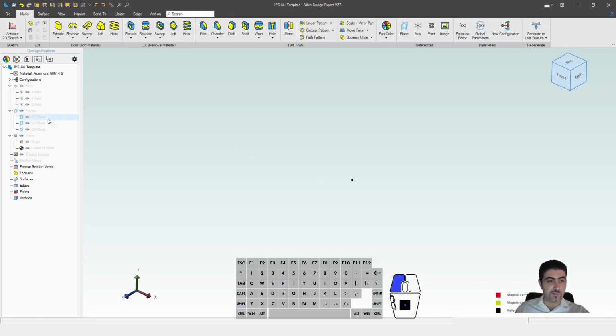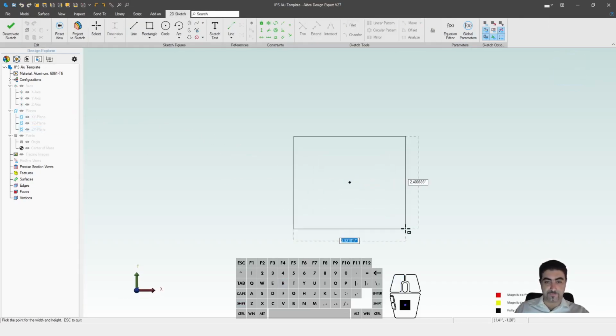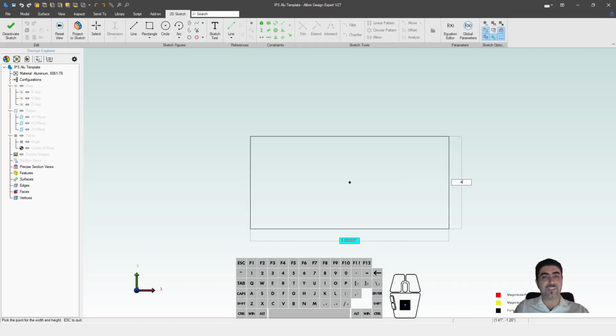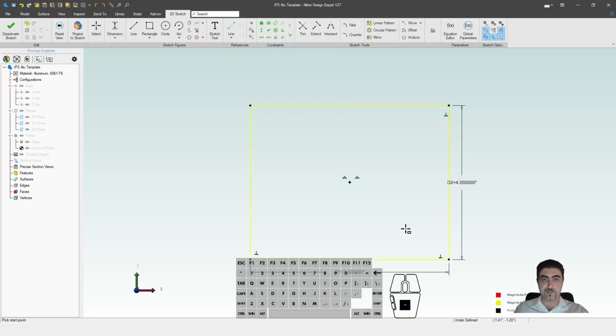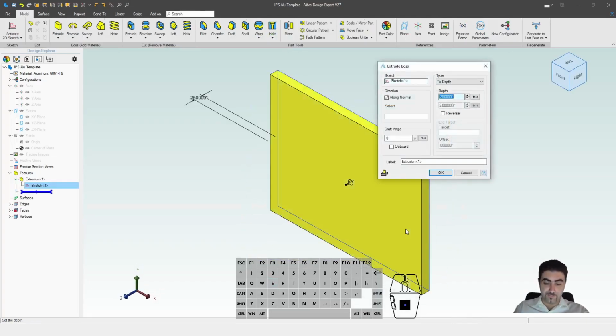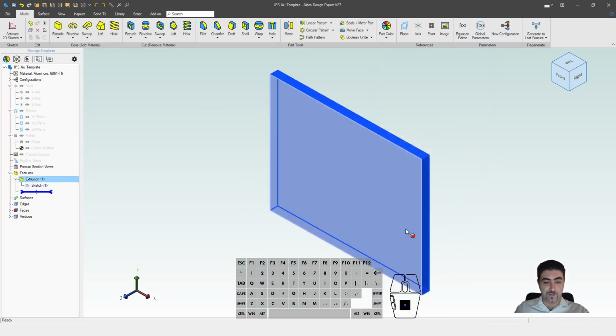So Shift R, I select the XY plane, right? 5, 4 is now a hotkey, so I need to use the numeric pad. Tab 4. Okay, now, I don't do tab again. I don't care if this sketch shows me a correct preview. I just hit enter, right? E dot 25, enter.